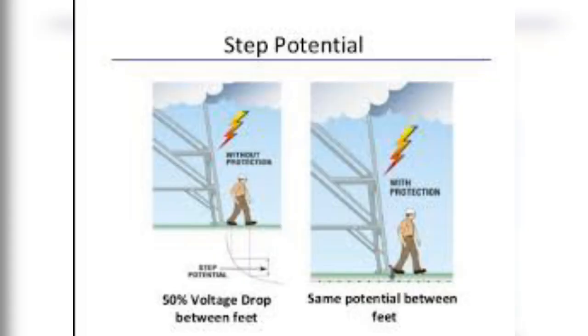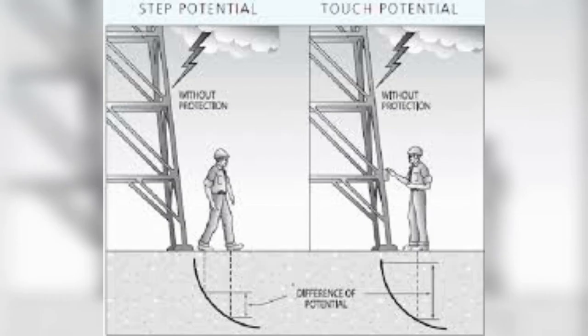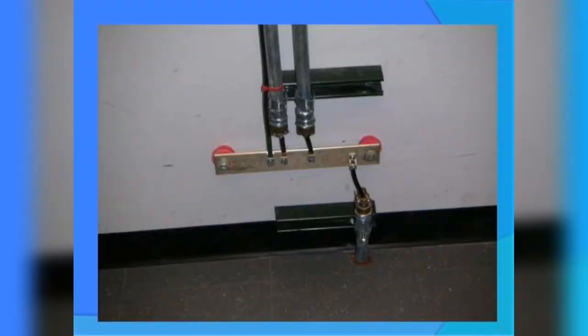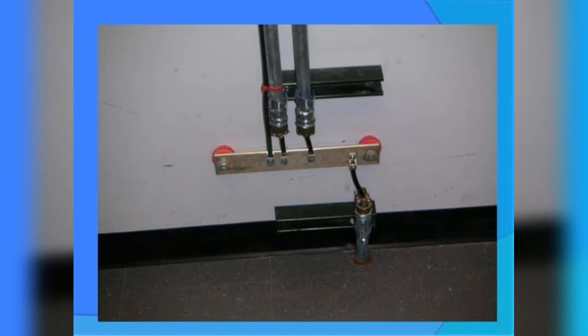If the geometry, location, grounded electrode, local soil characteristics, and other factors contribute to an excessive potential gradient at the Earth's surface, the grounding system may be inadequate from a safety standpoint, despite its capacity to carry the fault current in magnitude and duration permitted by a protective relay.